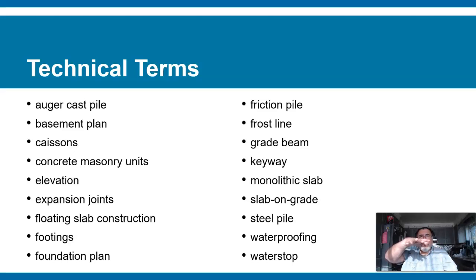So if there was space, it would try to hold itself up. It's just a way of distributing weight so that areas that have a lot of strong support will carry the areas that might have some soft support. And that way you don't get cracks in the walls or cracks in your foundation due to the ground settling.